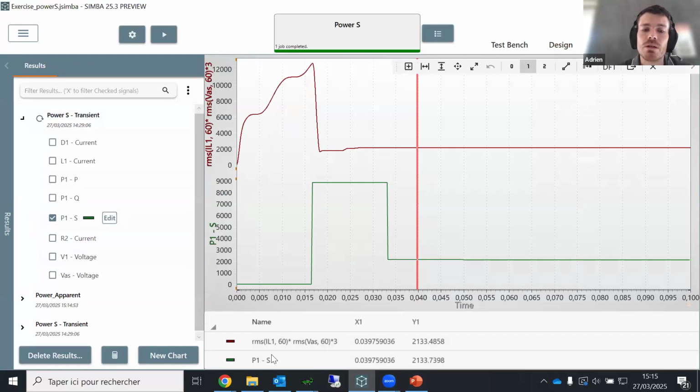So it's just to show you, we have the probe available directly with the block, or you can make any mathematical operations and manipulate all the signals together in order to get the same result. So I guess this tool will help you a lot if you want to manipulate signals, and if you don't want to use Python, you can do everything now in the graphical user interface.